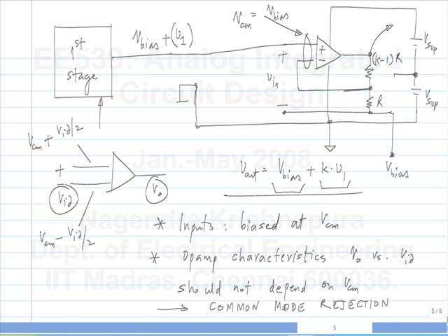Maybe with a 1.8 volt supply, it could be between, let's say, plus 0.1 volt and plus 1.5 volts or something. But within that range, if the V-bias is very small, the op-amp cannot make the common mode equal to it. If the V-bias is very small, meaning very small compared to the desired value of the input common mode of the op-amp.